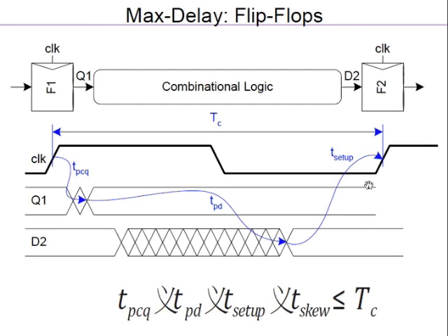There is also a concept of hold time. That means when the data comes, before this captures the data, but during the time it's capturing, you want to hold the data. If you change the data before it is captured, you will basically not get the data. It's like the lift is closing, and you come out of the lift. Now there is no one in the lift, so you are not in the lift. So it's the same thing.